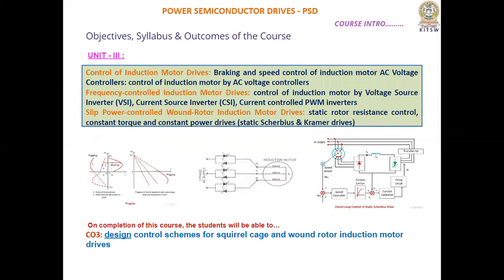Unit 3 is the control of induction motor, and hence we'll study the induction motor drives using AC voltage controllers and inverters. We'll study in particular the slip power controlled wound rotor induction motors, with techniques called static rotor resistance control, constant torque and constant power drives, Scherbius and Kramer drives.